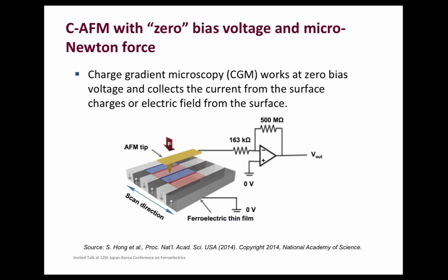So here it looks like a conducting AFM, but we are not applying electric bias, so there is no driving force in terms of electric force, but you only push hard and scrape it. Now, if you push hard, you obviously have piezoelectric charge, but that charge is very minor if you compare it with the scrape charge.